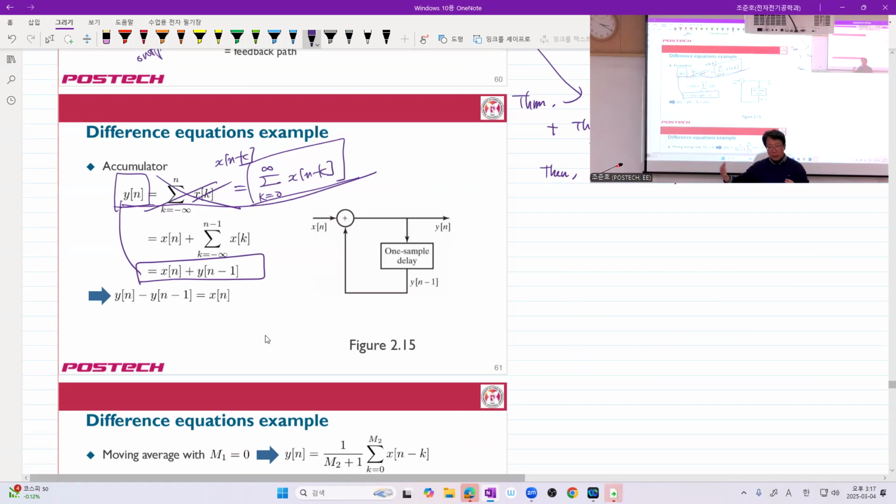In that case, each delay requires one delay component. Now, can you have countably infinite delay components in your implementation? No. That's why some people say, let's require LCCDE to have finite terms. That significantly reduces its applicability. However, when we want to implement it, it's very easy: we always have a finite number of delay components.